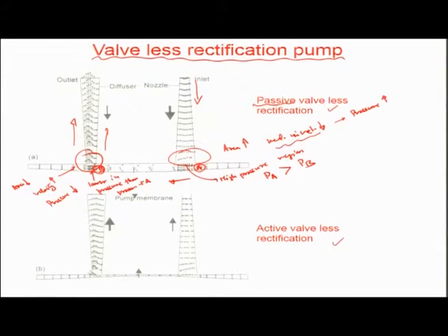These principles are actuation principles based on fundamentals of reduction in area and increase in velocity at different points along a channel, and such architectures could be drawn to passively do some actuation of fluid flow from one end to the other end by virtue of change in cross sectional area.